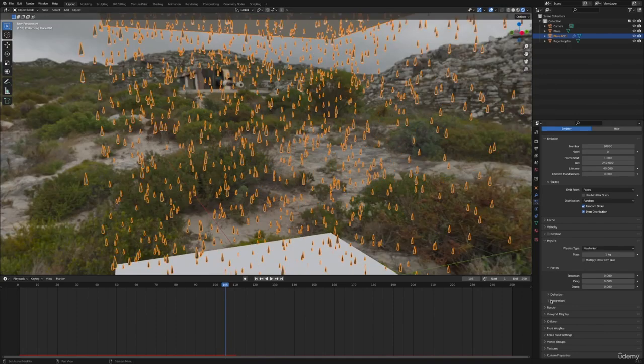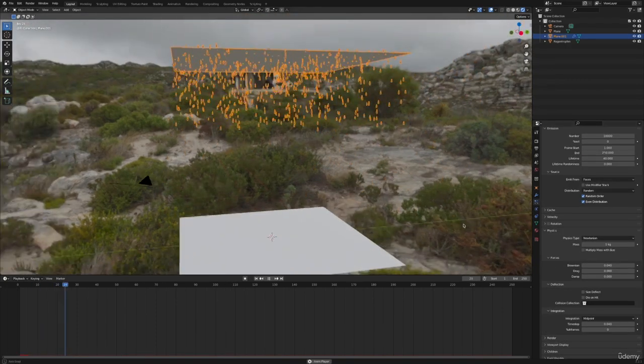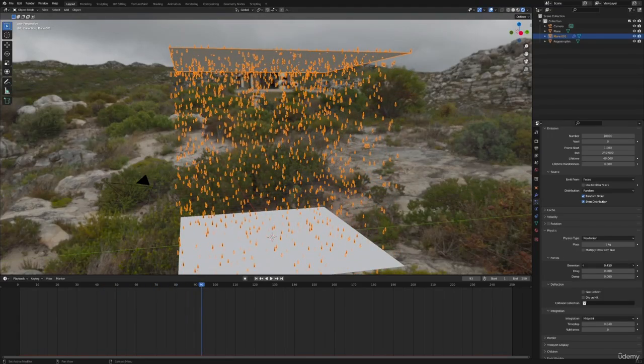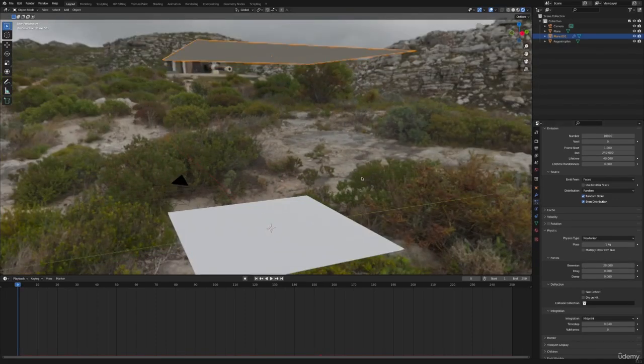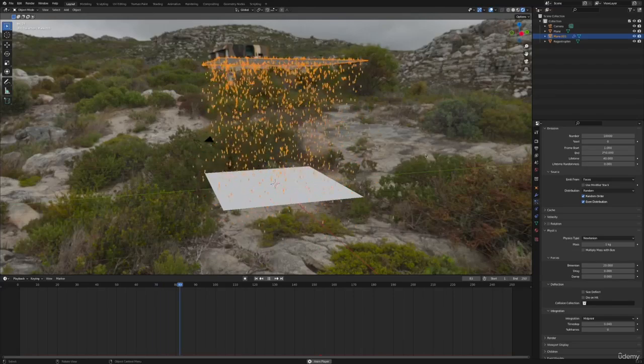But actually, there are many other options under the physics option that you can use. For example, different forces. There's the Brownian force, which, when we turn it up, causes our raindrops to be deflected a bit. It scatters them. And that means there are still a few left and right past our plane at the bottom. And if I turn up the Brownian force even more, you can see what happens. Our raindrops are basically falling past our plane on the left and the right.